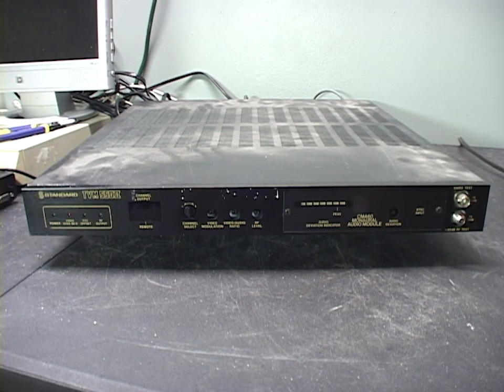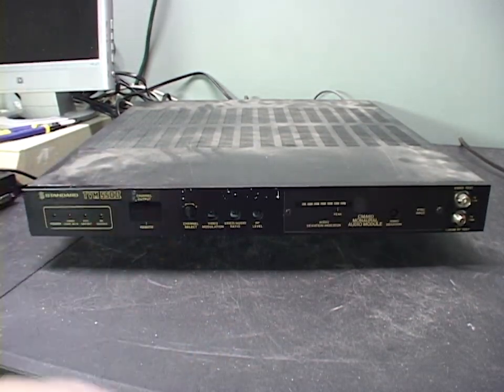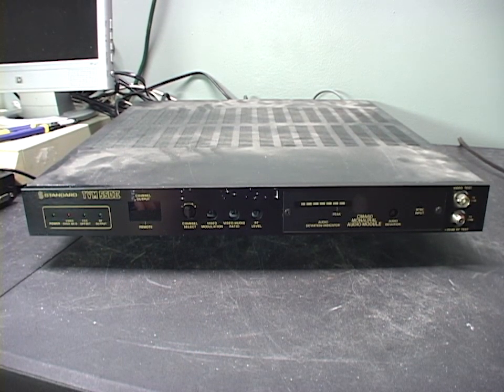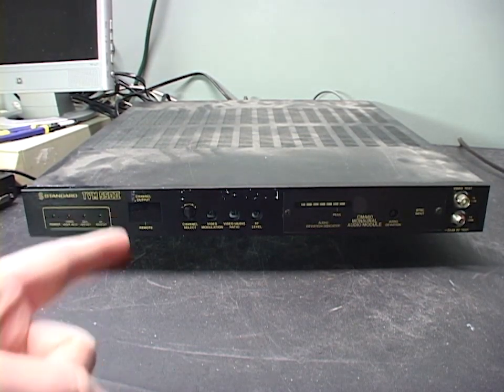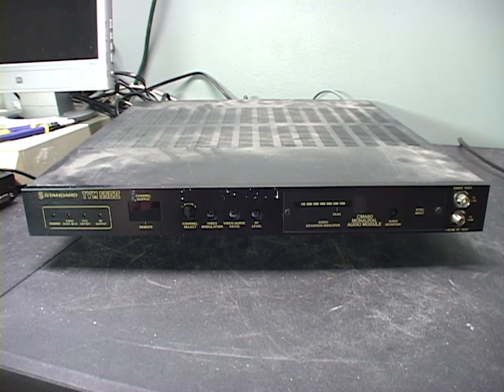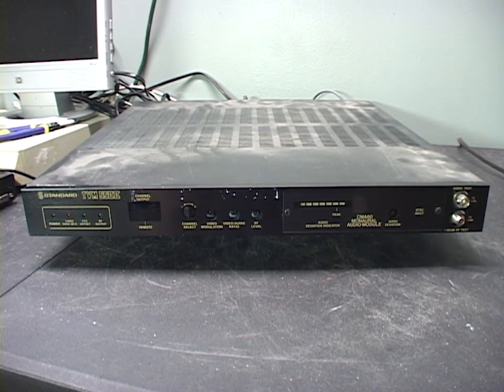Because see, a normal RF modulator, you've seen little boxes that you can plug a composite video signal into and modulate it onto channel 3 or 4 usually. Those output a signal strong enough to go directly to a TV, but if you try to send it over a long distance, you're going to get at best a fuzzy picture. Well, these output a much stronger signal than a standard consumer RF modulator. So they're able to send a signal over miles even, and the signal will retain perfect quality.